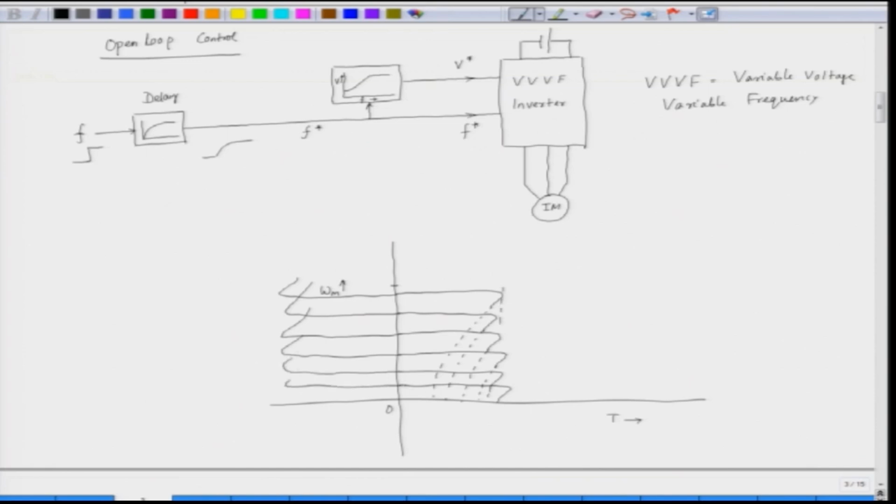So, this is the maximum torque. This maximum torque is almost constant here, T max, and this is the negative of the maximum torque. If we say this is T max 1, this is minus T max 2. So, this is for the braking or for the generating, because the torque is negative here, and this is for the motoring. So, this is the family of curves when we go for a variable voltage and variable frequency control, maintaining V by F constant.